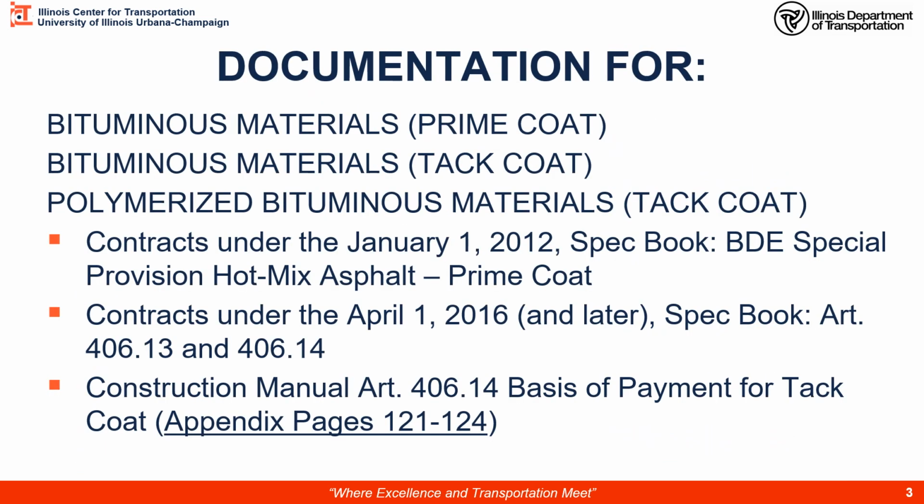Let's cover documentation for the various bituminous materials. We have a prime coat and a tack coat. You could also have a polymerized bituminous material as a prime or tack coat. The first special provision developed was from the Bureau of Design and Environment as a BDE special. That was incorporated into the April 1st, 2016 spec book, and I doubt there are any older jobs that utilize the BDE special provision at this point.